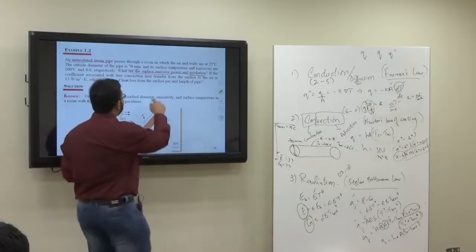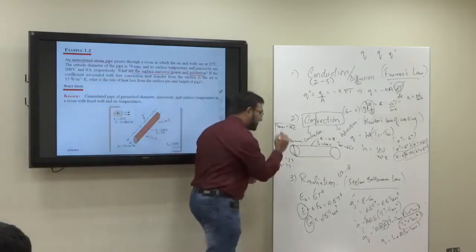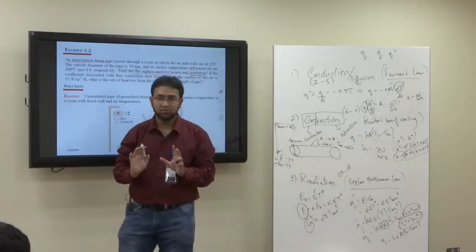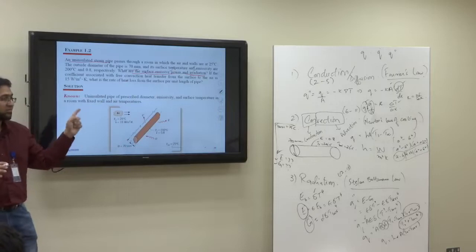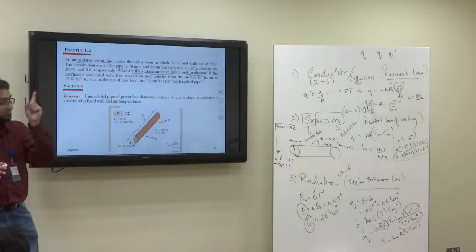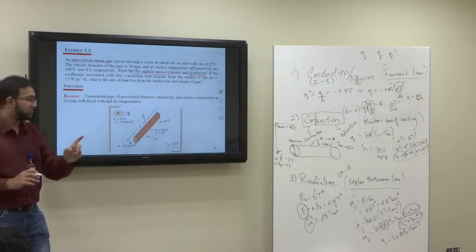So we can find what is the emissive power, we can find what is irradiation, E and G. Done? Anything which is not clear in it? But remember here, both need temperatures, and temperature must be in Kelvin. If you put the temperature in degree centigrade, big mistake.